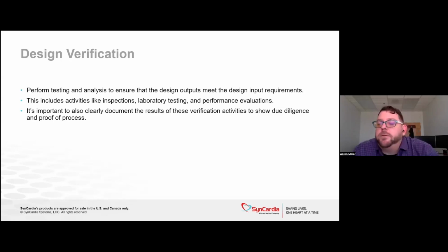This is where your design verification comes in. You go and you put your heart on the mock tank, you connect your driver, and you run it. Can my driver with that battery sustain 120 beats a minute for 6 hours in a hot environment? That's really your design verification. You look at your product requirements, those things that you were designing, and you make sure that you actually met them. This is likely going to be done with some kind of laboratory testing, benchtop testing.